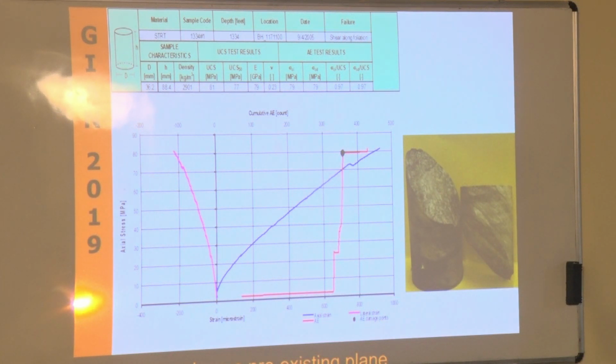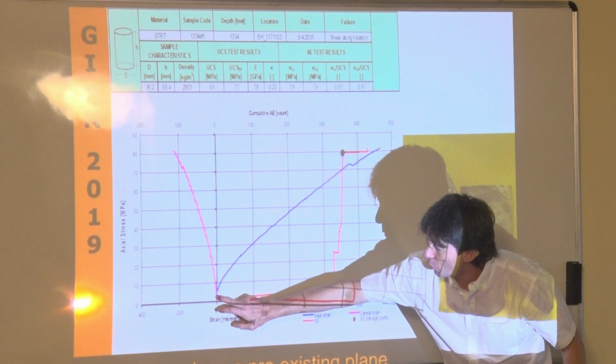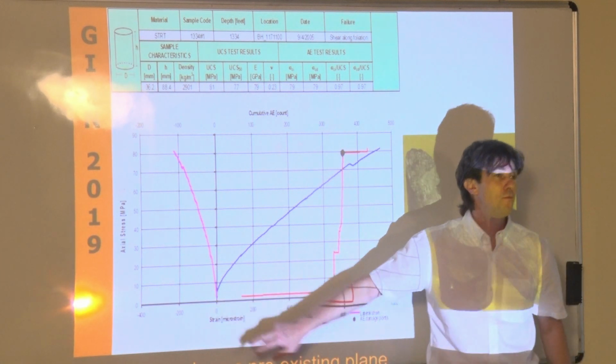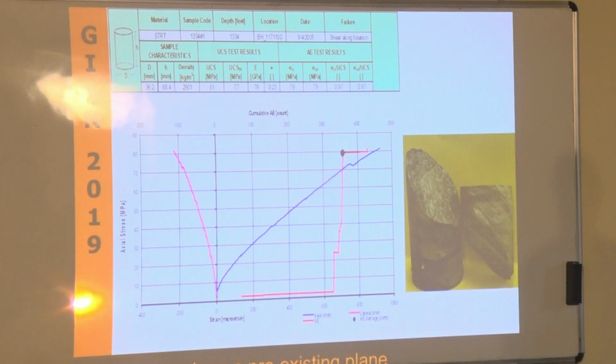Those waves go through the sample and they deform the sample, and by deforming the sample, they create a strain. Those really small strains are measured and used to calculate the shear modulus and Poisson ratio. But the problem is that we are working in this area, so a very, very small strain.